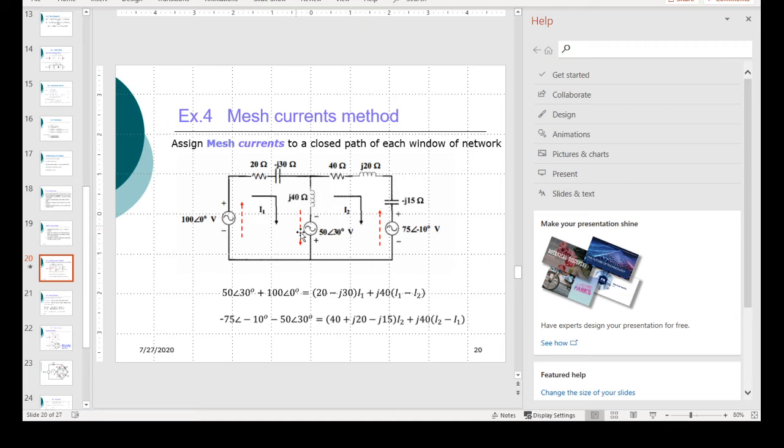Then the current that flows in the shared element, this is where sometimes there's a little confusion, is an arithmetic summation of these two. With respect to that, this current is flowing down, but this current will be flowing up, opposite to this. So the net current in this, when we are looking at mesh 1, will be I1 less I2.